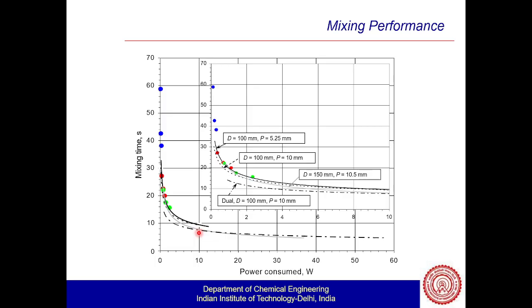Initially I said that our main goal is to optimize or increase the efficiency of the reactor. From the hydrodynamical aspect, we are increasing the velocity to make it more mixed. So now if I put reactants inside it, they will come in contact with each other, which will produce products with a higher conversion rate, and this will make the reactor more efficient.